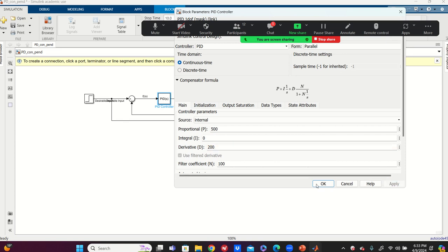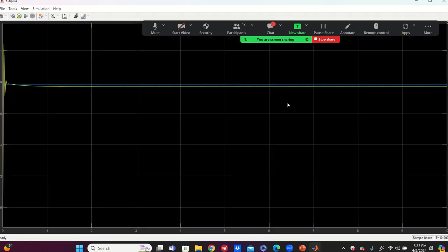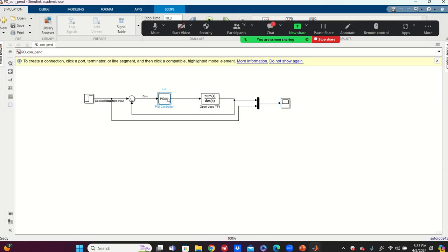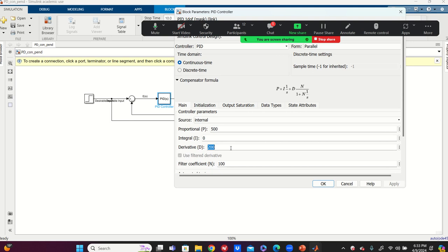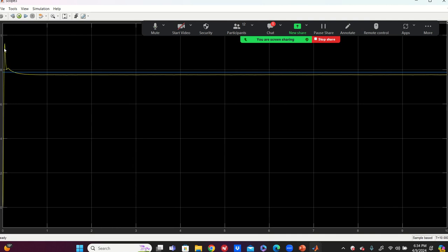200. So this is very close, but it has actually increased. You have to take it down because this becomes so much more noisy. Don't forget, the D controller adds noise to the system. Let us keep it at 50. Okay. Yeah, it's coming down a little. If it decreases a little more, it's coming down, yeah, eventually. So now you are very close to the target.